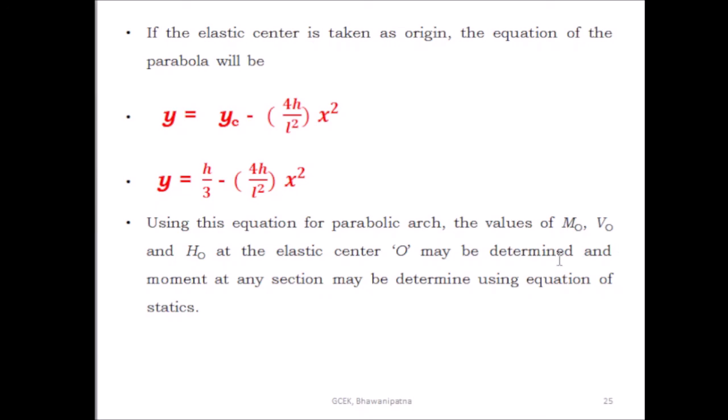Then the moment at any section may be determined using the equations of statics after getting M0, V0, H0 at the elastic center.